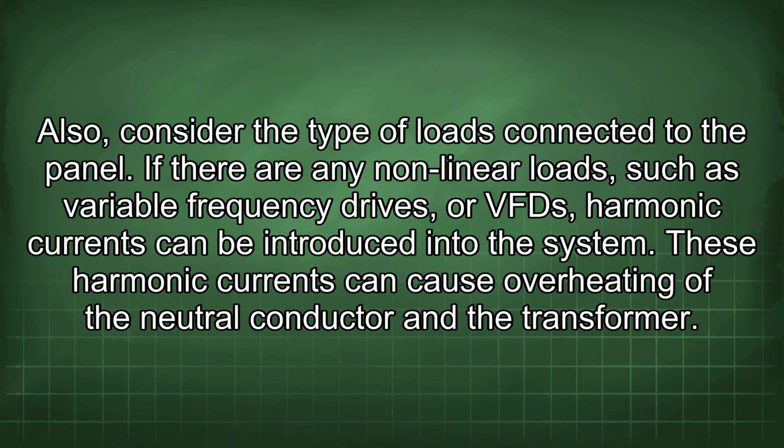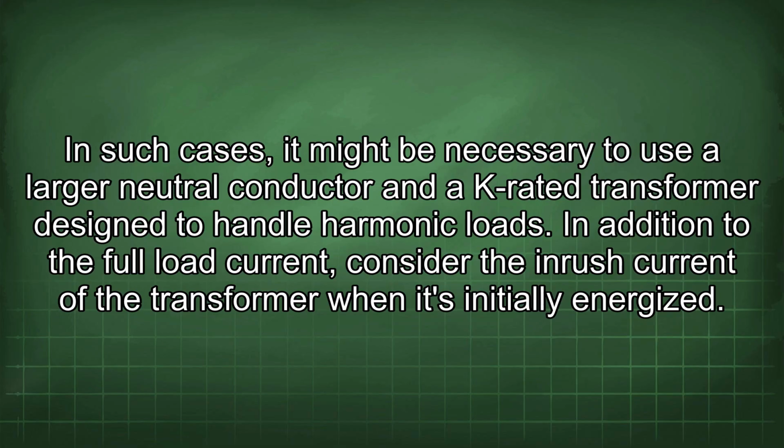Also, consider the type of loads connected to the panel. If there are any nonlinear loads, such as variable frequency drives, or VFDs, harmonic currents can be introduced into the system. These harmonic currents can cause overheating of the neutral conductor and the transformer. In such cases, it might be necessary to use a larger neutral conductor and a K-rated transformer designed to handle harmonic loads. In addition to the full load current, consider the inrush current of the transformer when it's initially energized.